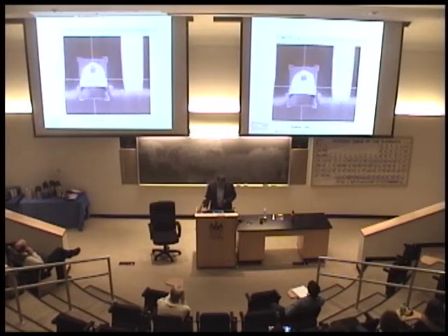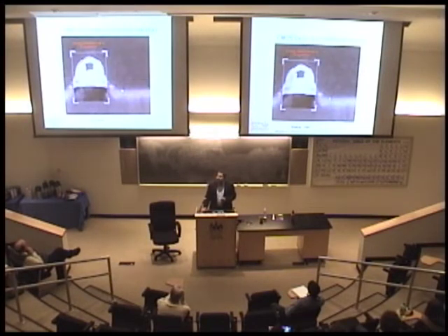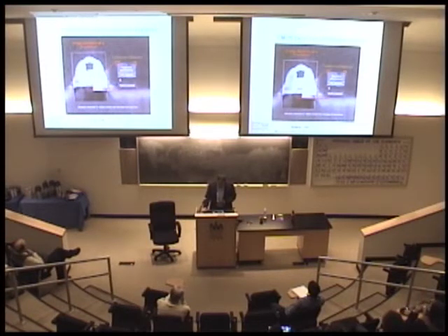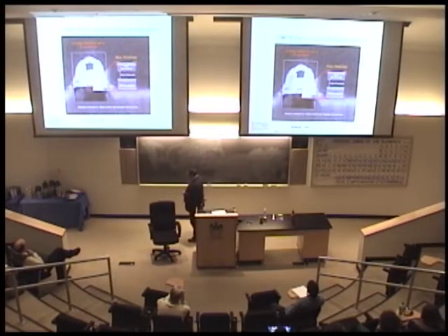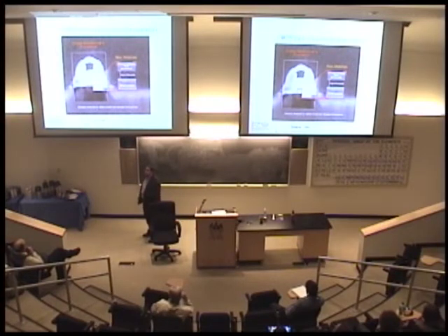Here we are, our chip, and here is the CMOS device. The thing that I'm talking about, the small gate part, is the insulator, the gate dielectric. That's the electron microscope imaging: the silicon dioxide, which is the gate insulator part, that's the silicon, the semiconductor, and that's the copper conductor. One of the problems before 2007 was that silicon dioxide was a physical limit.